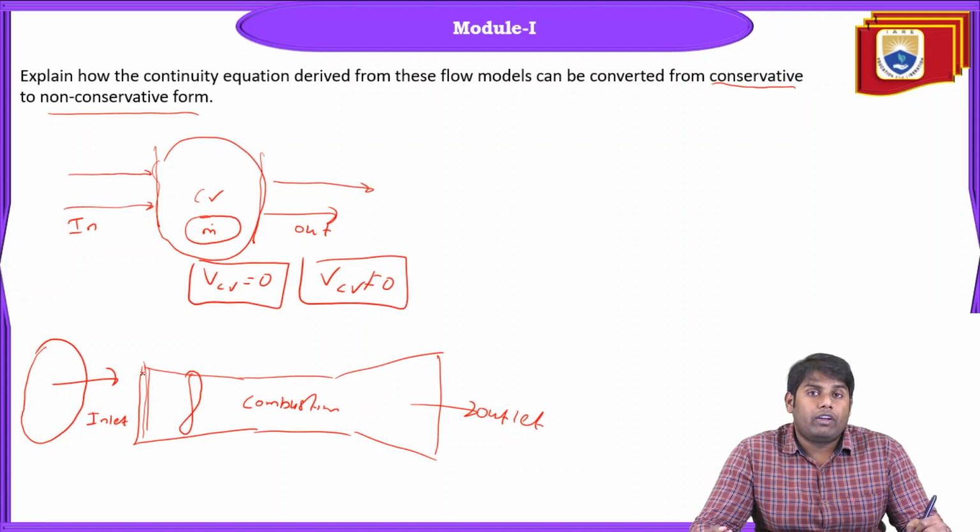So when the velocity is reduced, according to Bernoulli, what happens? There is a rise in pressure. And when there is a rise in pressure, in turn there is a rise in temperature also. Okay. So why we decelerate is, when the flow velocity is reduced, we guide that flow to the compressor to further raise the pressure.